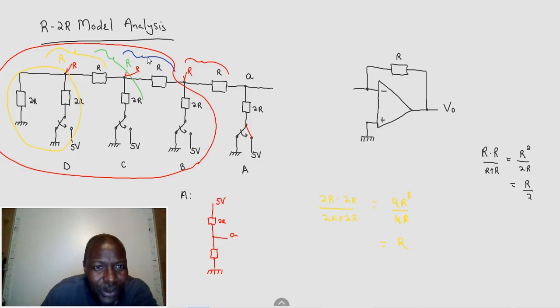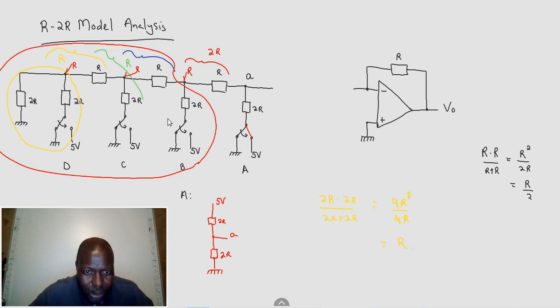After we see how all of this reduces to a simple resistor, because of being connected in parallel, which is just 1R. And that 1R is in series with this R, and we've got 2R here. That is the 2R that we have here. It is the equivalent of the whole circuit from R up to there, because they were all parallel. So they kept reducing until they were just 2R. So now we have a very simple circuit.